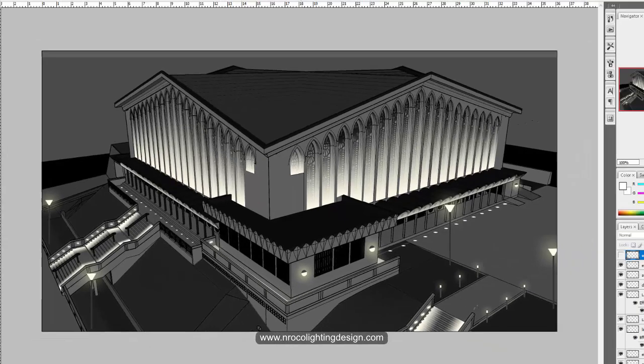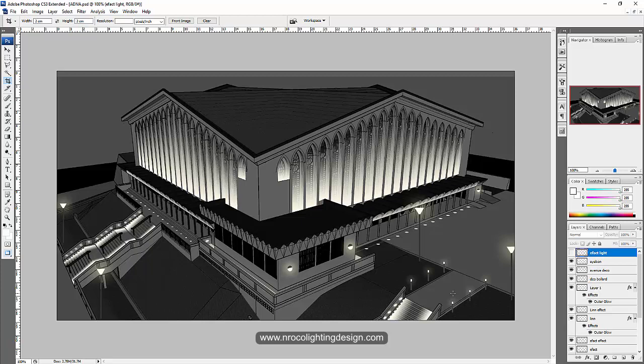And that's it. That's how easy it is to do it in Photoshop, actually. It's so powerful for the presentation, and it's very fast. But be careful in selecting the luminaires, because it might be overlit. Because they have mentioned that they want to highlight this decorative roof canopy and make the building brighter at night, you can overlay for a while, and then reduce or remove something if it's too bright in actual or in the simulation, or you can also check that if there's a mock-up.